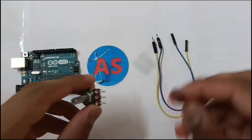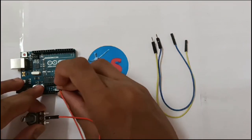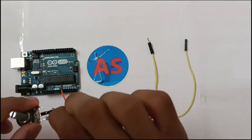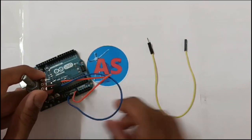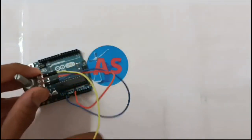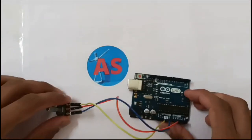So first we will connect the wiper terminal, that is the middle terminal of potentiometer, to A0 terminal of Arduino. Then we will connect one of the power terminals of potentiometer to GND of Arduino. Then we will connect the other power terminal of potentiometer to plus 5 volt of Arduino. So this is the overall circuit.